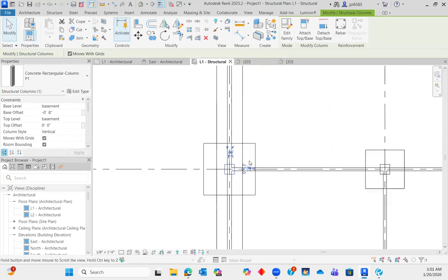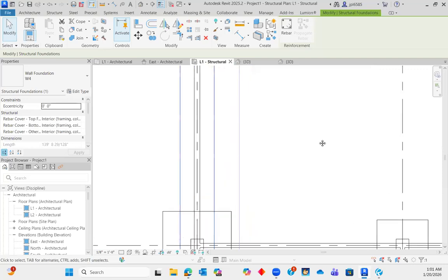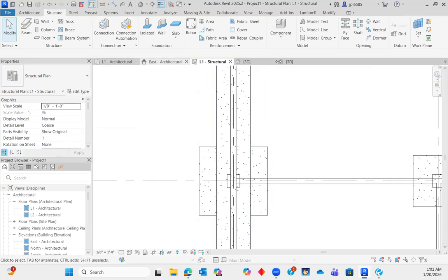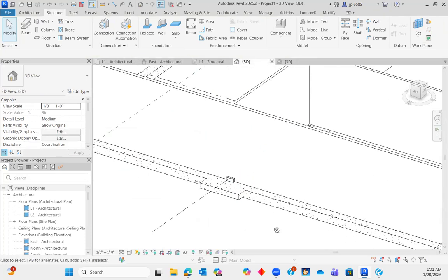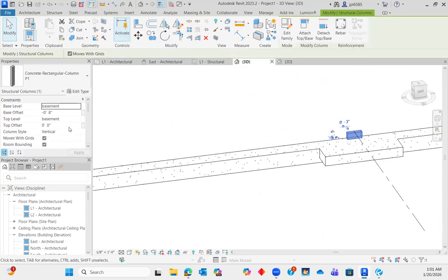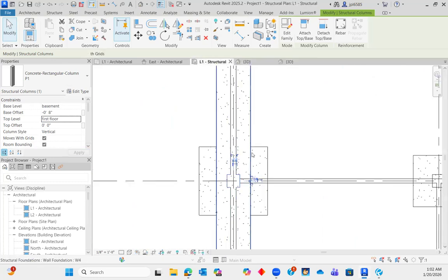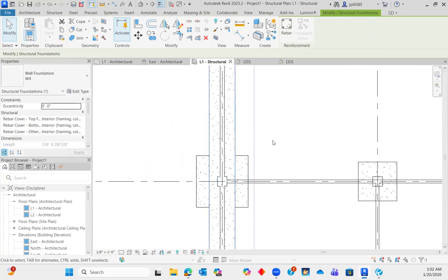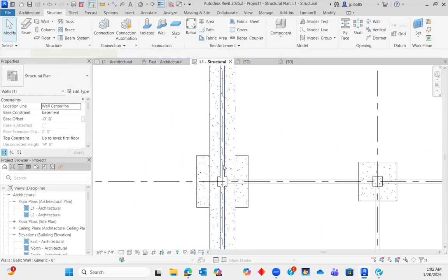And so your wall is going to control your spread footing. So I want this wall to be at negative 14.8, so I got to put it at negative 14.8 myself. And that's going to make sure that everything's at the correct elevation. So everything's at the same elevation. They all seamlessly blend. I wouldn't worry about it right now if it doesn't blend nicely, kind of like how it does before. That's okay. This is okay to have. We know that they're at the same depths.